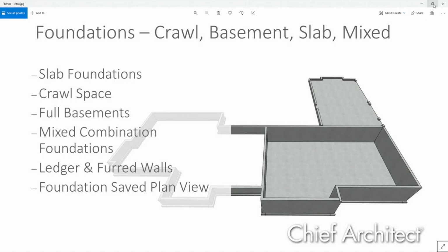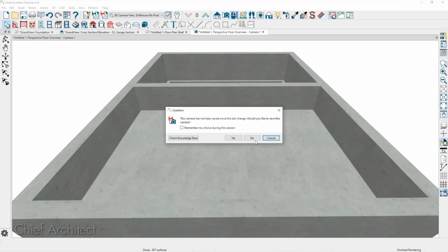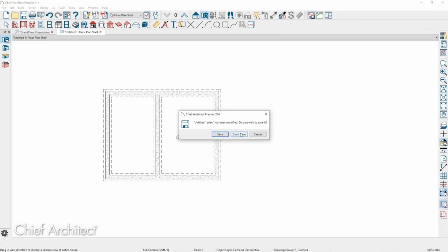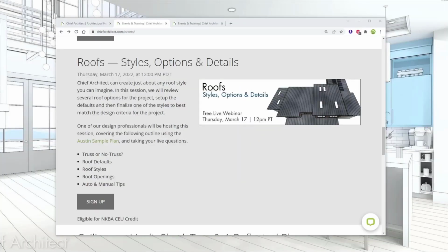So I've resorted to using a bearing line, but it then gives me the framing because I've used the post feature, the post with footing, and I've just deleted the post and used that whole thing. But what happens is it still doesn't generate automatically. It doesn't generate a foundation because I guess it doesn't recognize it as a rule.